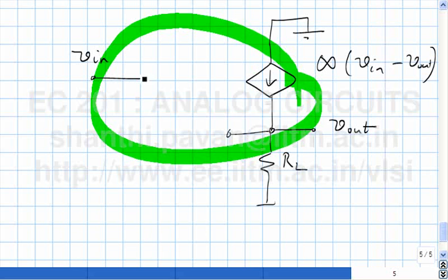The resistance between the base and the emitter, the incremental resistance, is missing. Okay, that basically assumes that the beta is infinity. You understand? So which is the base, which is the emitter, which is the collector now? This is the base, this is the emitter, the collector.